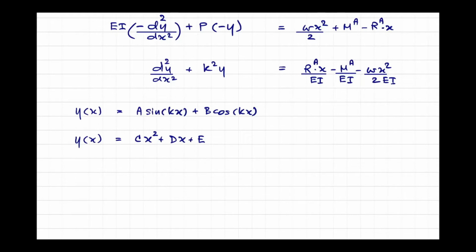So do not use the program and believe that it is going to produce exactly the same behavior as your structure. You need to look into your structure and see if there is any possibility that other kinds of effects that the program cannot handle are going to happen in reality or not. The program can handle A, B, but your real structure will exhibit A, B, C, D. So C and D will not be incorporated in the program.